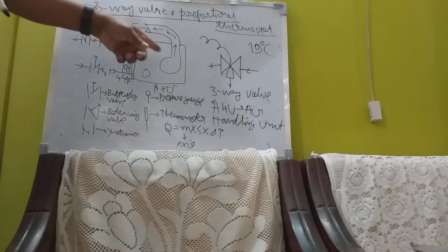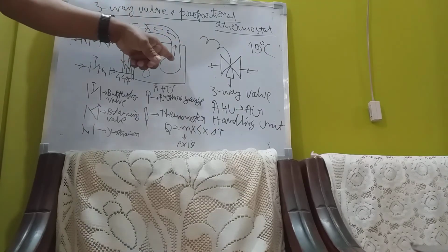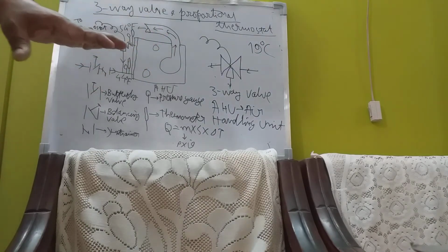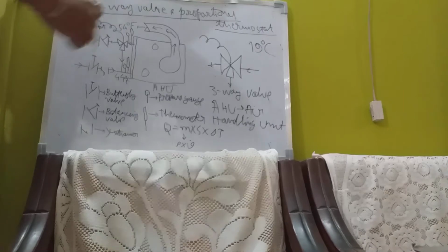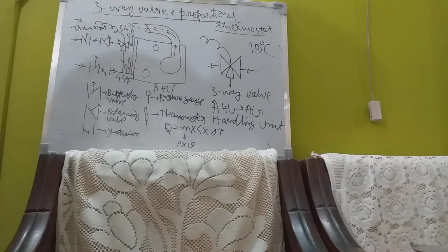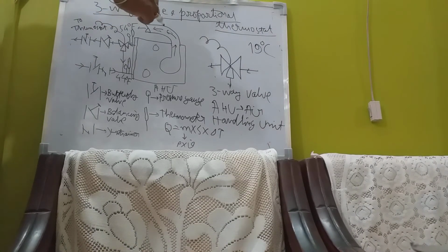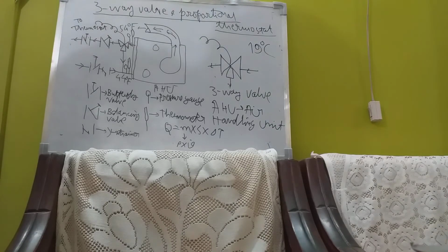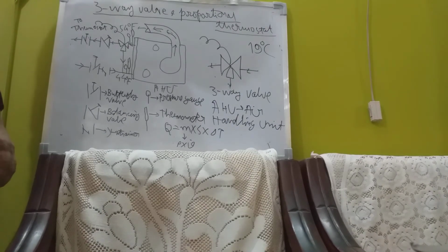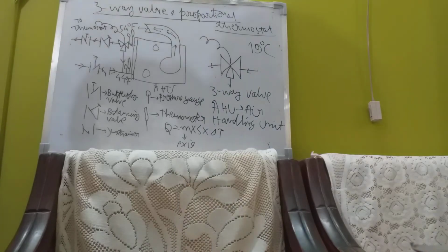And then comes the next thing, the blower. This is the fan of the system. You have already designed a blower. I told you the designing of the blower. The blower, this duct goes to the total system. So I told you about how the blower static pressure and CFM are to be designed. CFM means cubic feet per minute. That is the airflow.